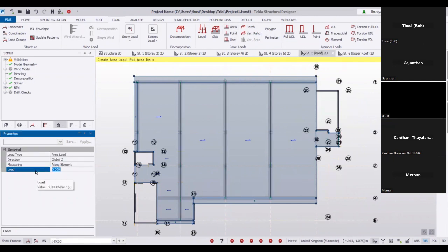I'm going to apply same. Actually, you can change it. Roof, you don't need any partitions, but in roof you normally need additional thickness of screed. Normally we allow at least 100 mm thick because you need a slope to fold the flow, right? To water to pass through it. So normally we allow 100. So 100 means 2.5 kPa. So I apply 2.5.